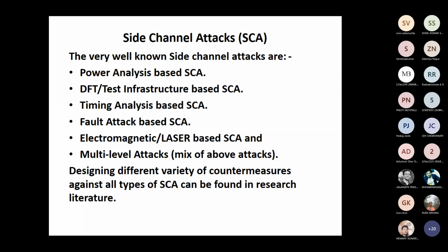It can also happen through timing analysis. As we have studied in microprocessor courses, we do timing analysis. Similarly, here also for the ICs, we can do the timing analysis. Similarly, DFT or test infrastructure based attacks, there also we can get the information. And fault attack based side channel attacks, or the electromagnetic waves that it emits, there also we can get this information. And then we also have multi-level attacks. When you talk about multi-level attacks, it means the attacker tries to get your information through a combination of two, say power and timing. They add them up and extract information from these.